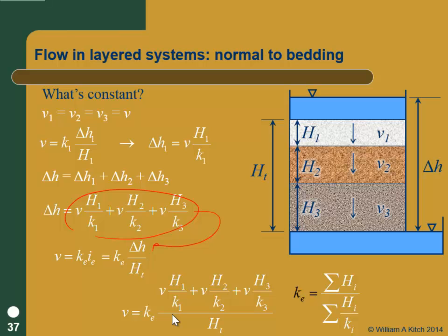Which you should think about. You go out in the backyard, you want to have a nice pool for your kids, what do you put down? A piece of visqueen, it holds water really well. Very, very thin, very, very low hydraulic conductivity. This is why clay liners work, very thin clay liners can work to control flow in a landfill or something.